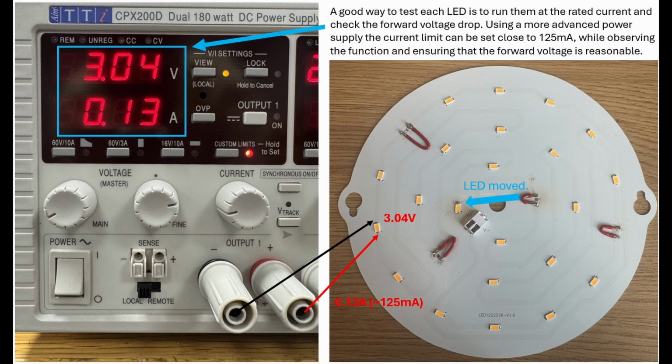With 11 LEDs on each side, we get 11 times 3 volts, which is the nominal for these LEDs. I still end up at 33 volts, which is within the spec of what the power supply can deliver. So the power supply should be able to deliver the 250 milliamp total at 30 volts. So this is how I set it up. I get a little less light, yes, but it comes out working, which is what I could achieve.